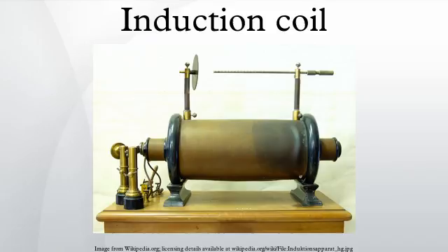The voltage developed in each subcoil isn't large enough to jump between the wires in the subcoil. Large voltages are only developed across many subcoils in series, which are too widely separated to arc over. To give the entire coil a final insulating coating, it is immersed in melted paraffin wax or resin, and the air evacuated to ensure there are no air bubbles left inside, and the paraffin allowed to solidify, so the entire coil is encased in wax.